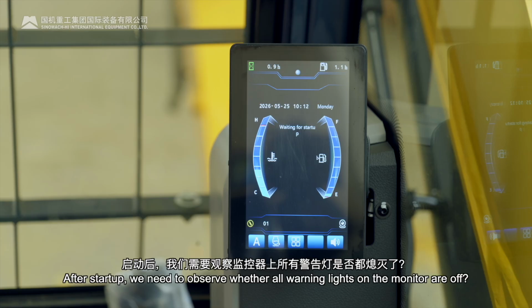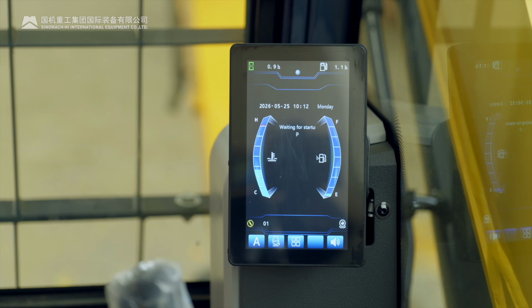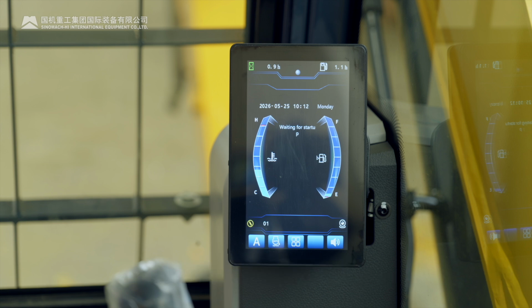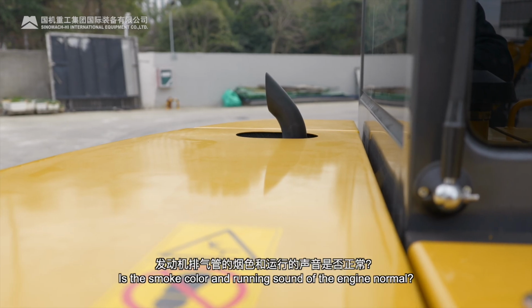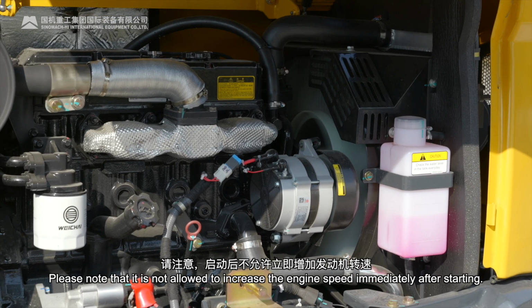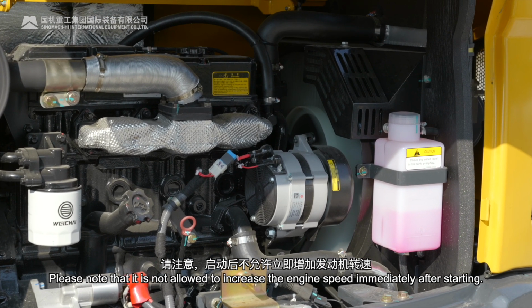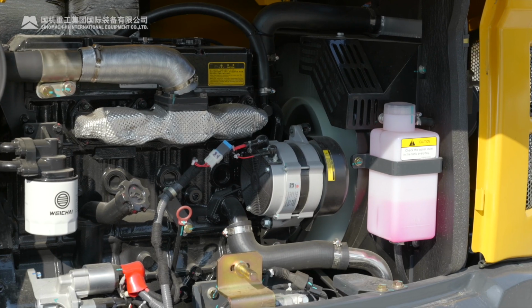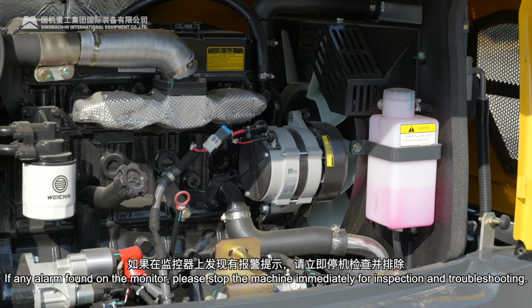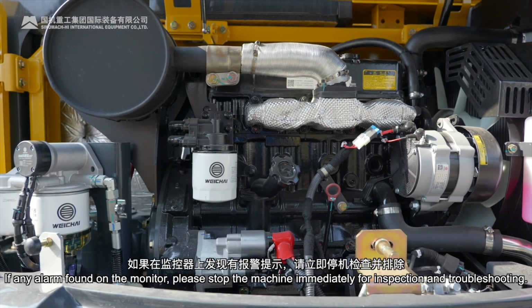After startup, we need to observe whether all warning lights on the monitor are off. Is the coolant temperature gauge within the normal range? Is the smoke color and running sound of the engine normal? Please note that it is not allowed to increase the engine speed immediately after starting. If any alarm is found on the monitor, please stop the machine immediately for inspection and troubleshooting.